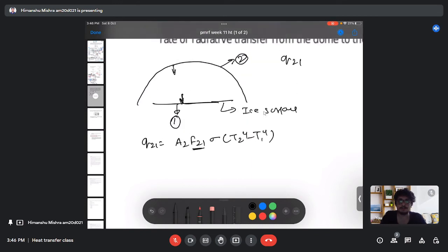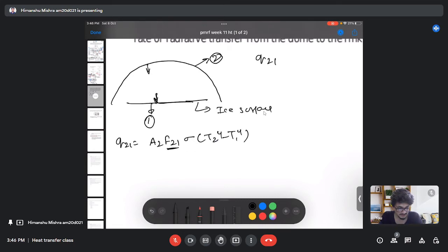We already solved many view factors for many geometric surface cases in the last question. So it is pretty clear by now how to use the different rules to find the view factor. Just by direct inspection, you can find that F11 will be 0. F12 will be 1, because all the radiation emitted from surface 1 will be intercepted by surface 2.